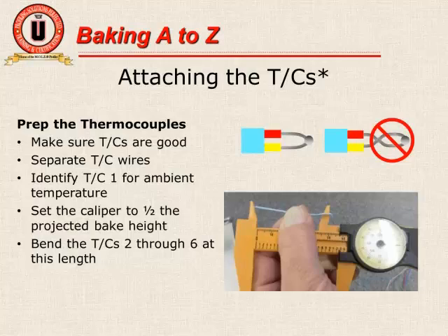It's important that the thermocouple have the two wires meeting at one point. This is where the temperature is measured, at the welded bead at the end. What you don't want is a bead and then an extra twist. Don't have these conductors connecting together at any other point along their entire length. Quite often the insulation, if you're not careful, will get burned or damaged just because of over-bending or too much bending. And if you've got a short along the length of the wire somewhere away from the bead, whether right near it or somewhere along its length, you're not going to get good readings.